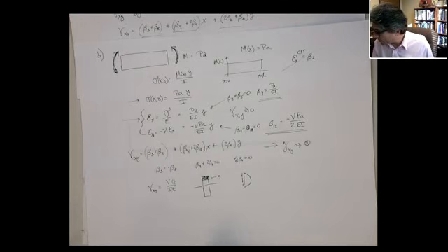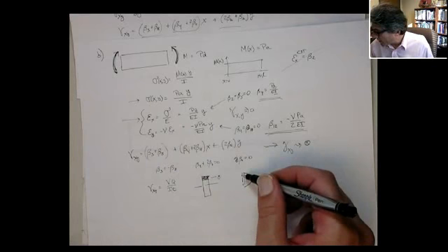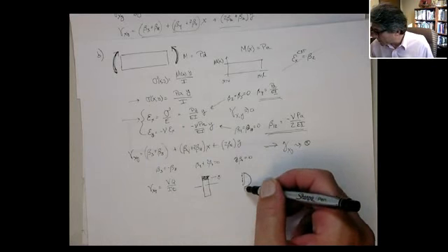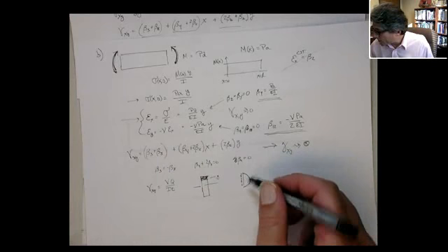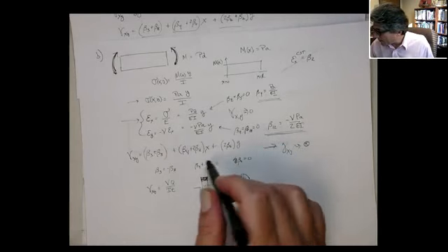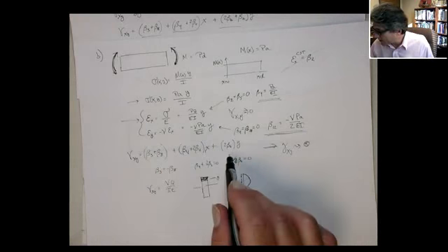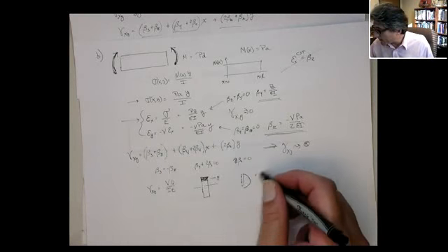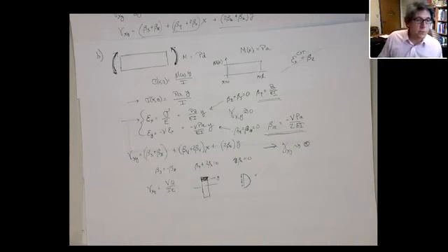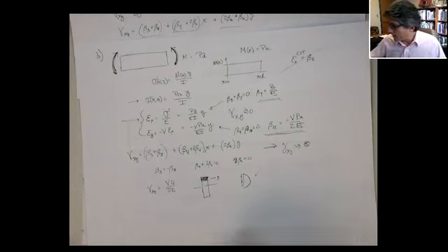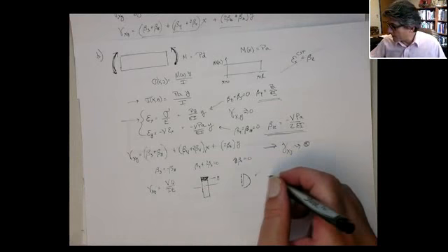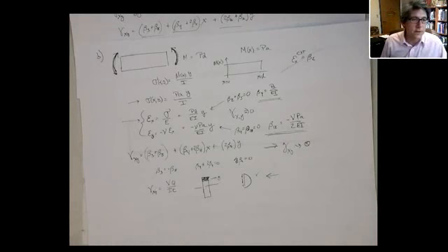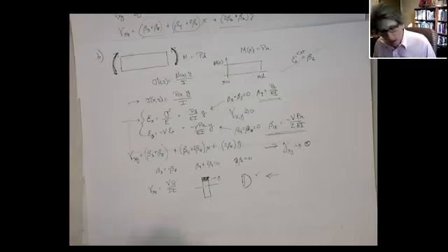V is constant. Well, actually, in this element, the V is 0, so it drops out. But in general, if you have a non-zero V, you'll get this quadratic distribution. And what you can see, though, is that because this cannot reproduce a quadratic, it can only reproduce linear, you will not be able to exactly reproduce the shear terms that arise from bending. Now, those are usually small, but when we look at planar elements, we will see that this will cause us some difficulty, okay? But it's not really what they're asking in this problem, okay? So we'll stop there.